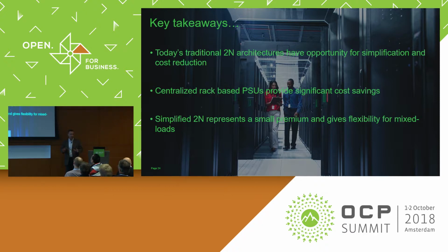So he's going to make sure that he's not going to be underpowered, and he's going to put 2 of them in there. Open compute, it's at the rack level, so you aggregate that, and you can be N+1. And it's done at the operational level. The person operating the data center gets to make sure that you put in the right number of modules to power that rack. So the oversizing from the PSU is much, much less than that.